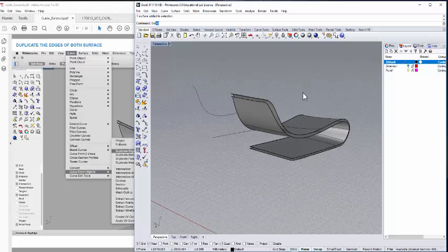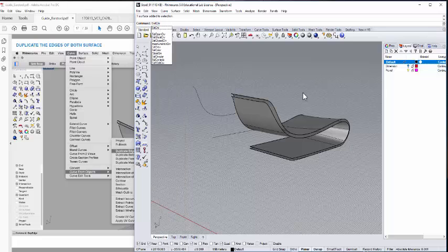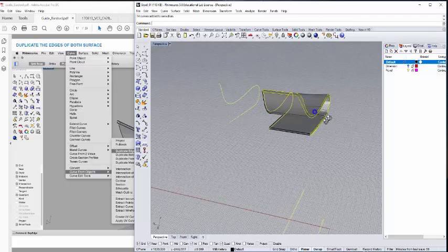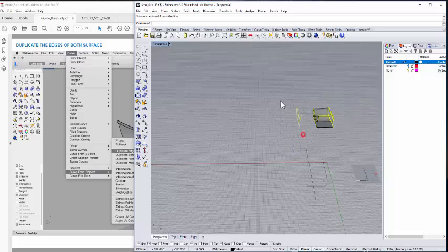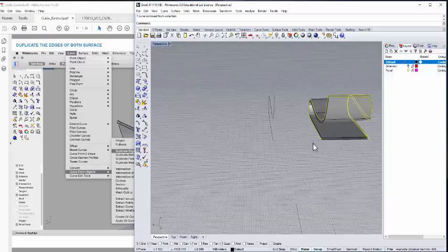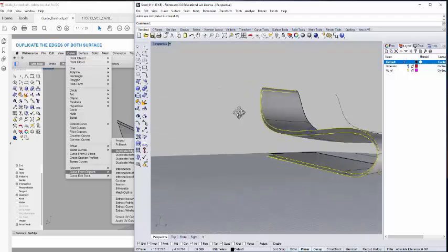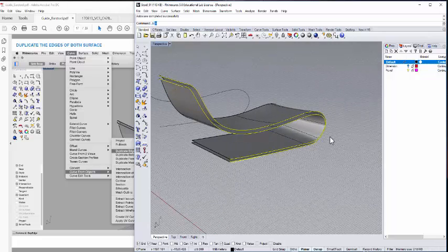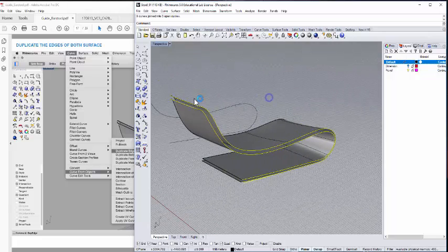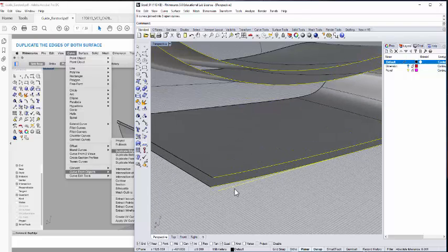Okay. Let's say for example, if you forget to do that, right now, and we are stuck here, right, what you can do is to select curve. Okay. Then you press Ctrl to deselect the curves that you do not want, which is all here. All here we want to deselect. Okay, so now we are selecting the duplicated curve. Just press join. Okay, so now 9 curves join into 3 open curves. The reason why is that we have one extra here.